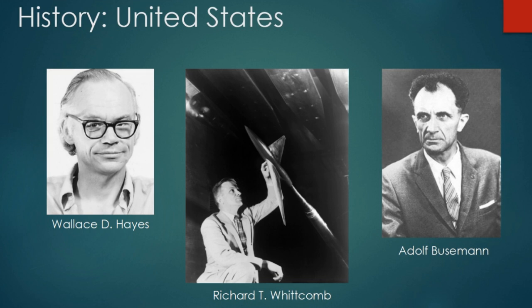Several days later, Whitcomb had a eureka moment. The reason for the high drag was that the pipes of air were interfering with each other in 3 dimensions. One does not simply consider the air flowing over a 2D cross-section of the aircraft as others could in the past. Now, they said, they also had to consider the air to the sides of the aircraft, which would also interact with these stream pipes.